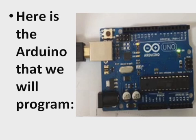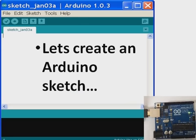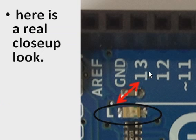Here is the Arduino that we will program. Double-click the Arduino exe on your computer, and let's create an Arduino sketch to blink the onboard LED, which is attached to pin 13. Here is a real close-up look.